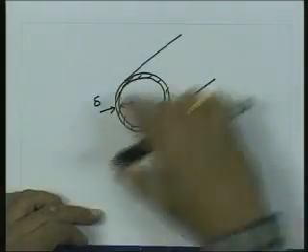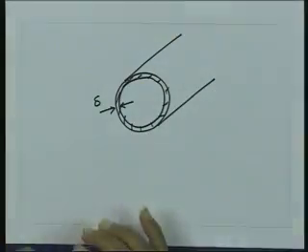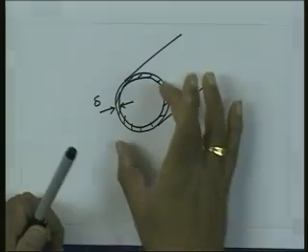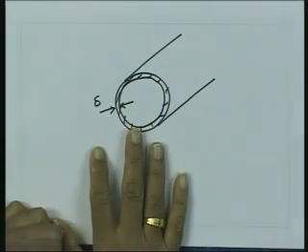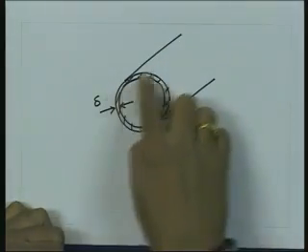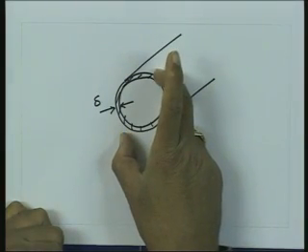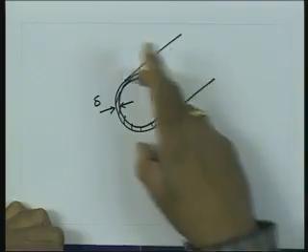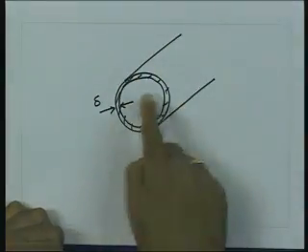Once we understand this, we find something interesting. Let us say we have a finite conductivity of this medium through which we were sending the signal along this conductor, and we have a certain area of cross section or radius for this. If I go to extremely low frequencies, the current will be uniformly distributed over this, so I can find out the area of cross section. From the area of cross section I can find out the resistance of this wire per unit length, because I know the resistivity of the medium.